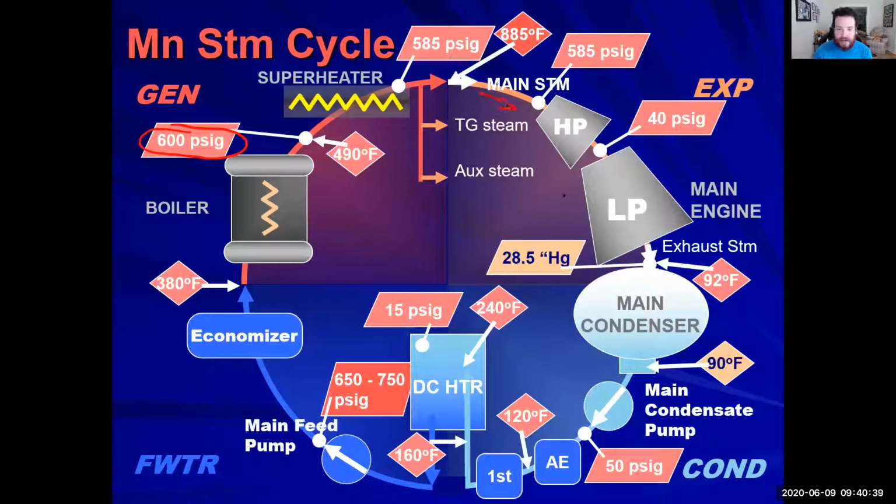the big thing to pay attention to is not to have these numbers memorized, but the understanding of what is happening there. Why your high pressure turbine is so much smaller than your low pressure turbine, and how you're getting almost the same amount of force and usability out of your steam in both. Whereas your high pressure turbine is built to withstand these high temperatures and high pressures.